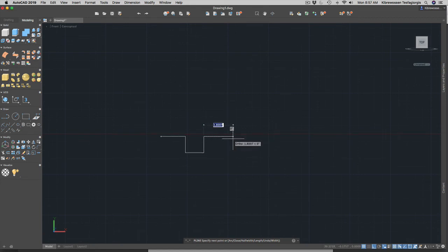and then go to this direction 1.5, and then go to 2, and in this direction you go to 4.13, then you go ahead and close it, type C and then press enter. Then AutoCAD will close it for you.